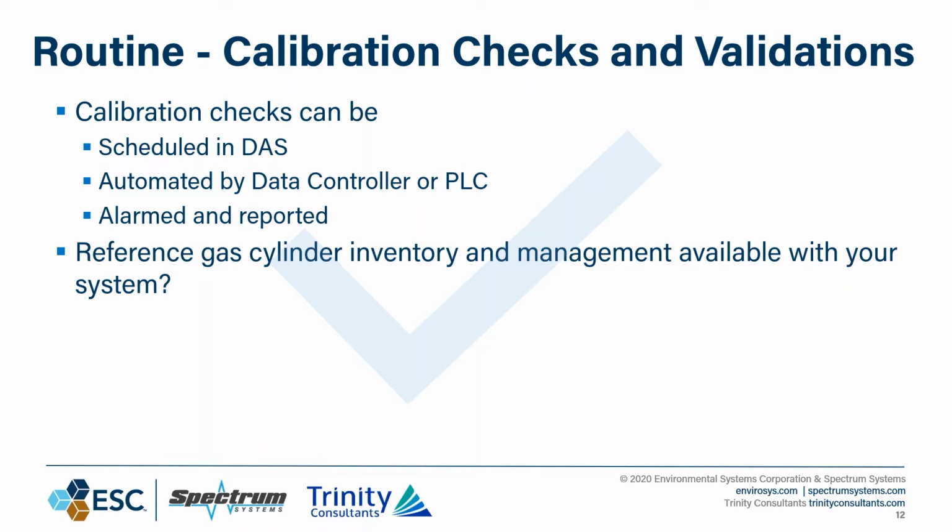Out in the field, failed calibrations are probably the most common thing we would see, and those calibrations can fail for any number of reasons. In your routine, if we see a failed calibration as a DOS auditor, immediately I'm going to be looking for evidence that you troubleshot from a maintenance perspective and a regulatory perspective. I'm going to try to find the entries in the logbooks that go along with the failed calibrations, because that's how you can get out of control quickly if you don't address it.